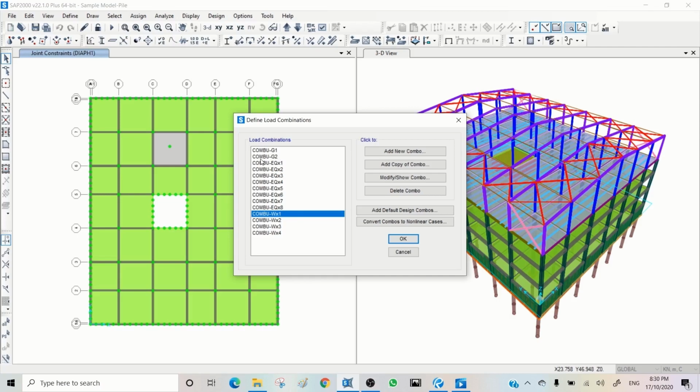Now what we have for working stress and serviceability. What's the difference between working stress and serviceability? Working stress is actually a fixed reduction factor compared to Ultimate. So working load is generally 67% of Ultimate. That means when you want to change all those to working load, for example, designing your pile foundations or pad footings for soil bearing capacity check, what you need to do,